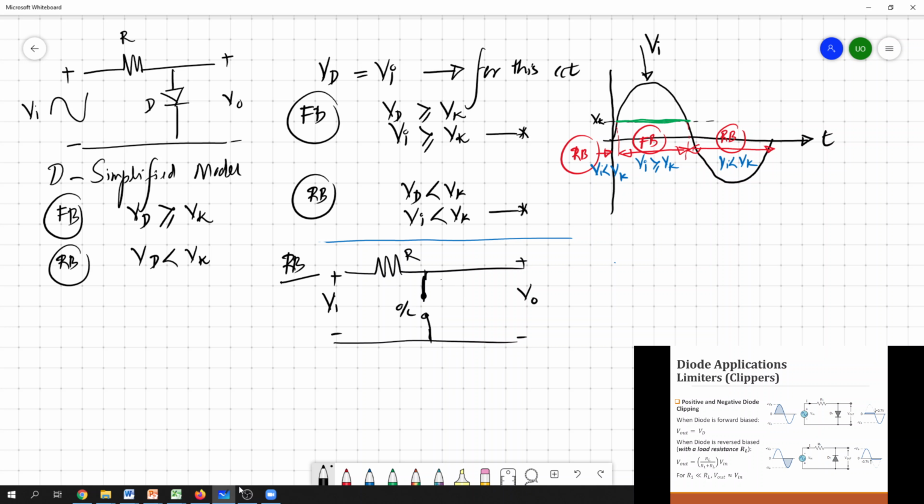So there won't be any current flow through this network, and the output should be equal to the input. You are just plugging a voltmeter here and there won't be any current flow through this one. The input resistance of the voltmeter is simply infinite, so there is no drop across the resistance, and you are just measuring the voltage across the source Vi.